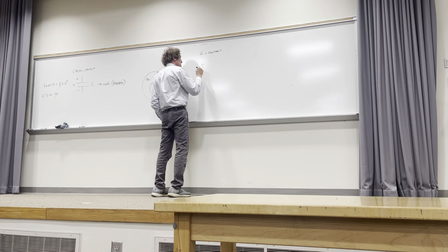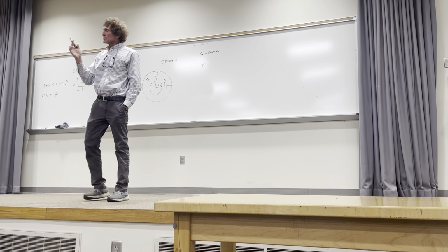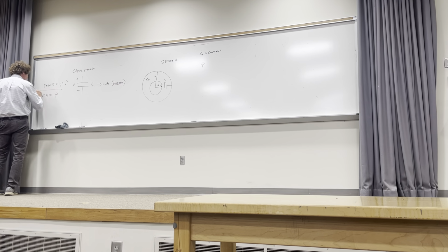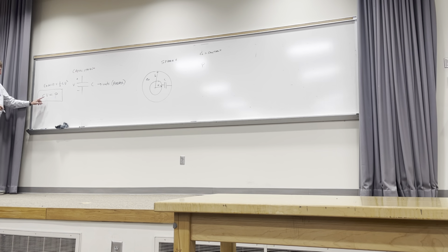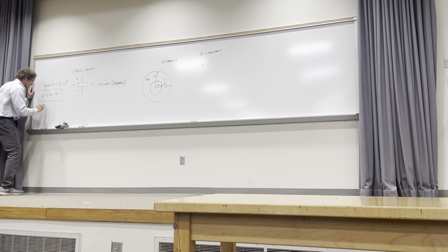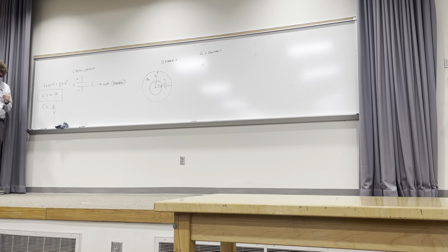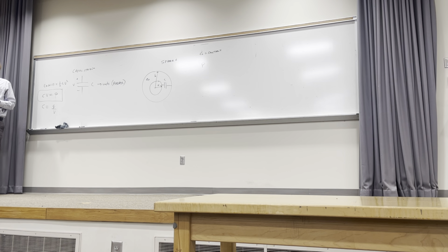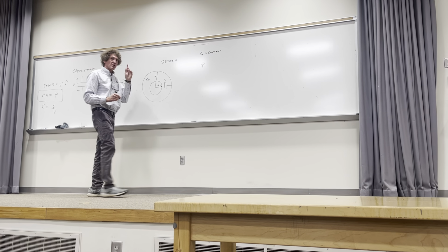When you start assuming either charge or voltage, typically charge, we're going to ultimately use this relationship. If we assume charge, then we get voltage, and we see the actual capacitance is Q over V. You all follow me on this, class? Everybody with me on this? It's just like the resistance calculations. We have to assume something, so we start by assuming Q.